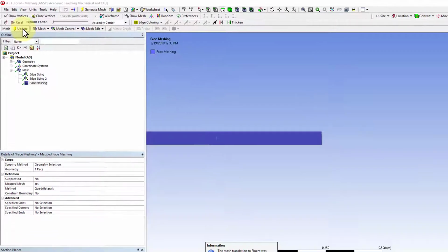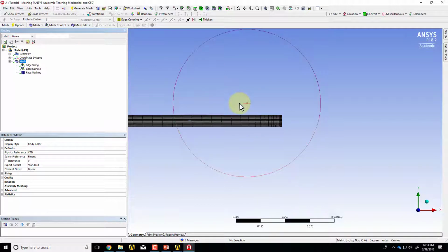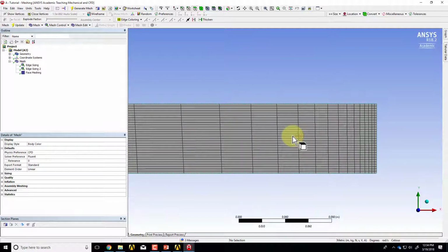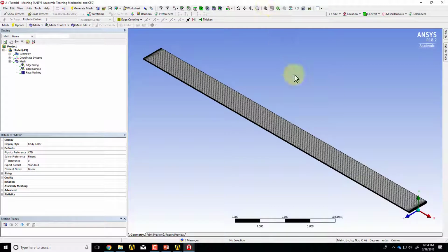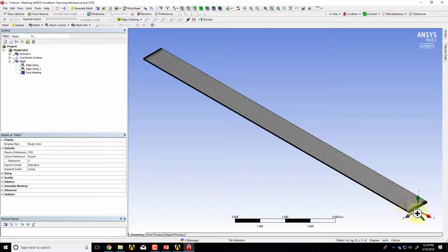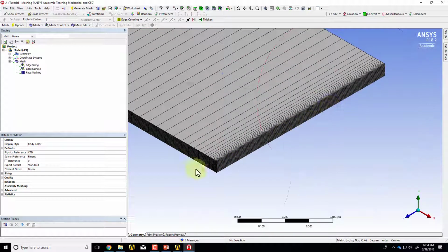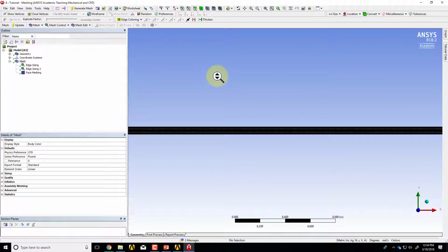And this might be familiar to you from the conduction tutorial if you've gone through that, or the laminar pipe flow tutorial. And then if I go to the mesh, now it looks rectangular, the cells, if I zoom in. By the way, if your model gets askew, you can zoom out here and then you can click on Z. And it shows me a 3-dimensional visualization. Our mathematical model is 2D, so ignore the 3D visualization.